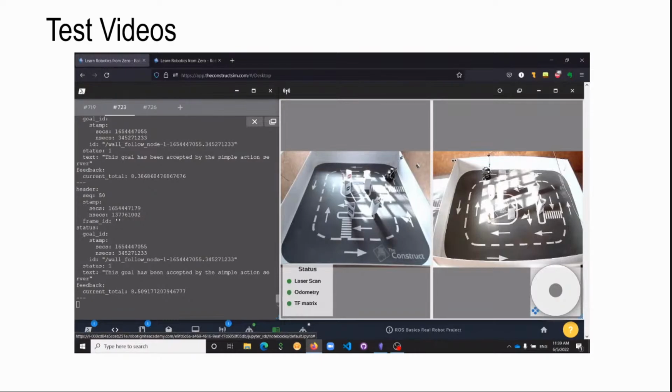Because I'm recording all the points that this robot passed by, I will calculate the distance from the latest point to all the older points. If I find that this latest point is very close to any one of those older points, and as of now the robot has moved more than 7 meters, then I call it the first lap.